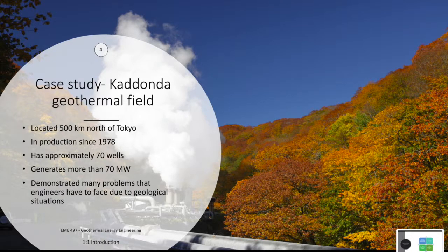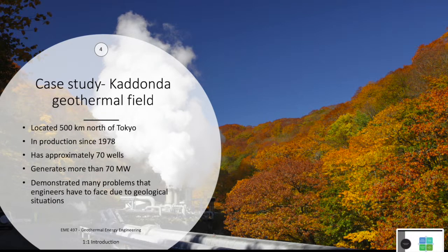As drilling continued, further issues were discovered at different depths. At 3,451 meters, the drilling fluid had deteriorated to a point that it needed to be replaced with one that had a lower density due to the temperature. It's important to make sure the drilling fluid works so you don't damage the drill string or the drill bit.